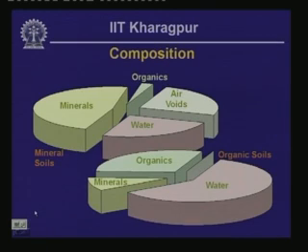Okay. Now on this slide we look at the typical composition of a soil mass. Soils in a sense are composed of solid grains. Then the soil mass will also include void spaces, and some of these void spaces can be filled with pore fluid, and some of it is going to be filled with air.